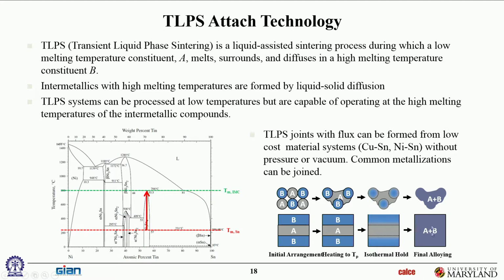The good news is that its CTE is pretty close to that of silicon. Most intermetallics are 5 to 6 parts per million per degree C. Silicon is 3 to 4. So there's not a big CTE mismatch with silicon, but there's a lot of CTE mismatch with everything else around it. So some of that makes it back into the silicon, and there's no stress relief because it's so rigid. So for example, if the board warps, remember I told you a package sometimes warps, this will transmit all the stresses into the die, no stress relief, and it'll fracture the die.